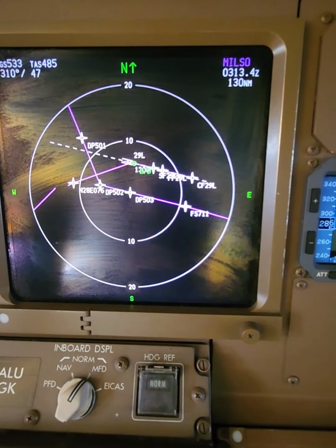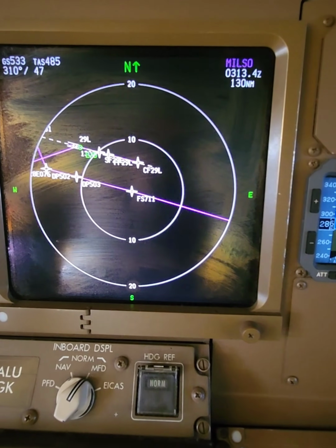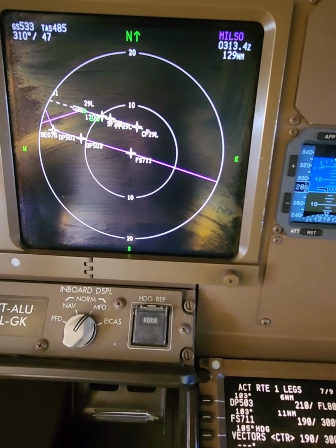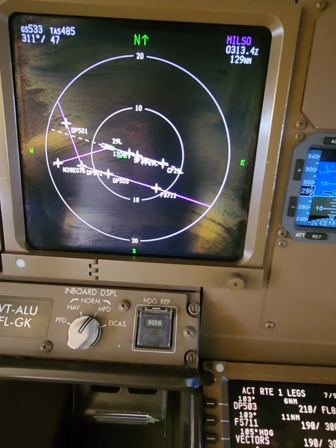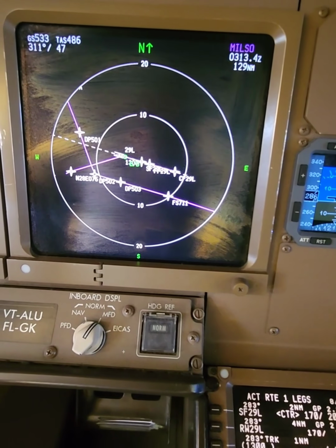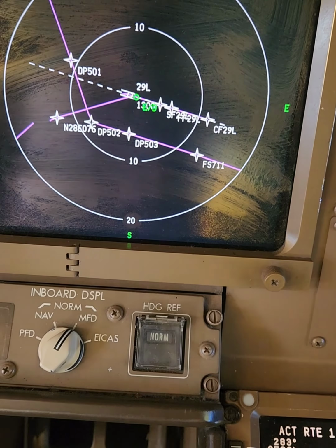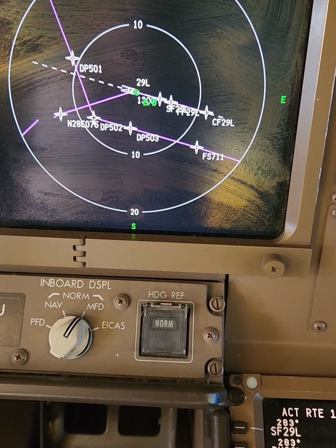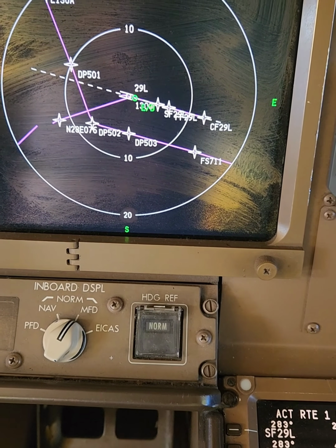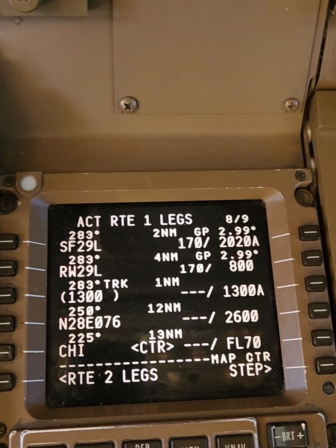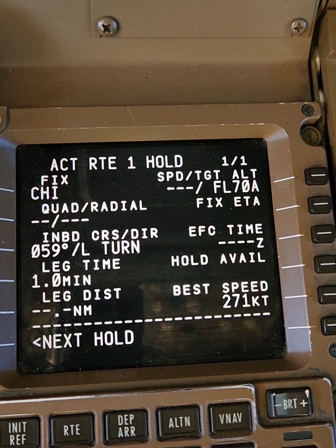Data removed on the EFIS, so time won't be shown now. If you want to know the timings and the other constraints of that particular waypoint, the data for that waypoint should be on the EFIS. So this is a very good helping aid. The white extended dashed line of the runway helps in non-precision approaches and will let you know the offset, like which side you need to correct on the VOR.